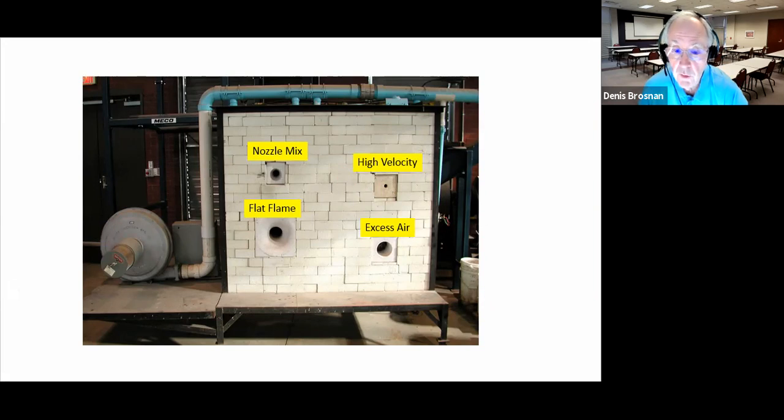And like I say, we're going to talk about the backside of this burner and trace the lines. Trace the lines meaning we go backward from the burner through the control valves, through the adjusting valves that we have available to us, through the shutoff valves, to the fuel source, and back to where fuel comes into the plant or the area of the plant that you're operating in.